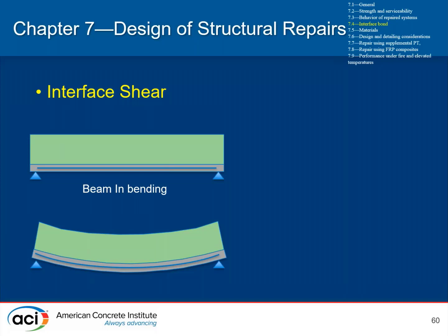If you recall, typical shear stress equations indicate the shear stresses that develop across different sections are maximum at the center of the section and taper towards the end of the section. So those shear stresses develop both from loading and, as mentioned, from time-dependent deformations that may occur from shrinkage.